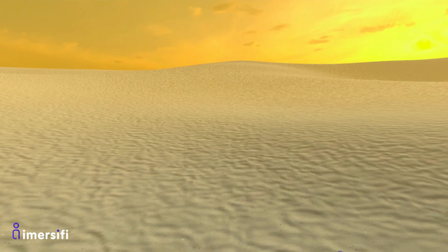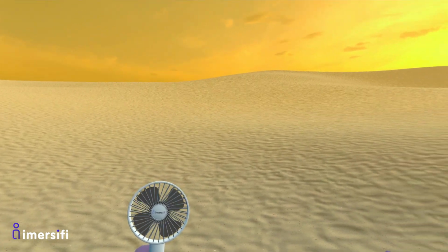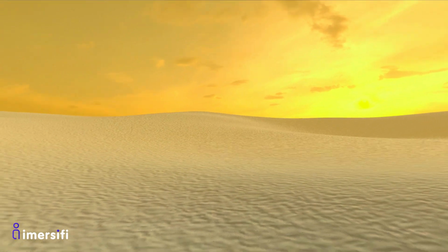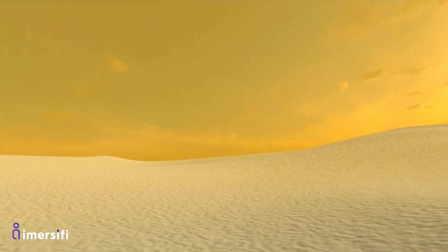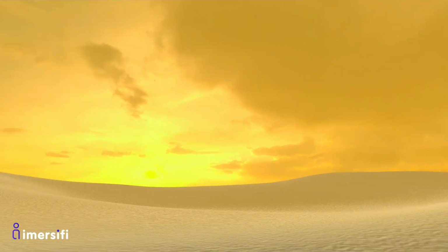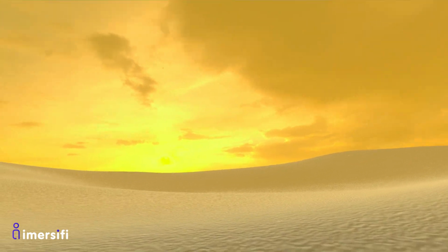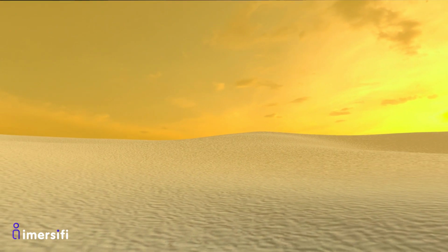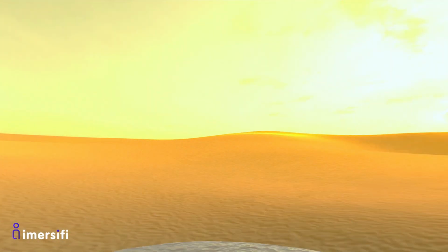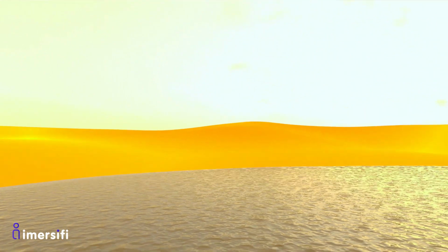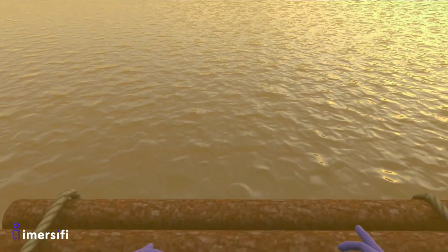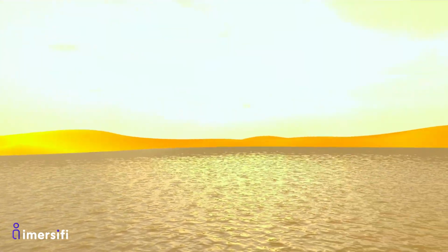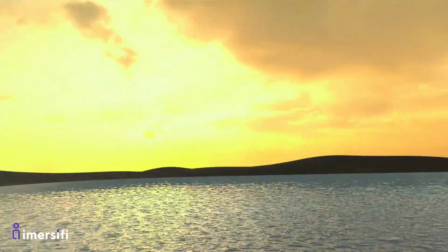Why do we find ourselves in the middle of a vast desert, under the scorching sun? Well, to make semiconductor devices or chips, the process often starts with sand or silicon dioxide. This sand is silicon-rich. When exposed to temperatures greater than 1800 degrees Celsius, the sand melts. The oxygen can be removed, and the silicon is purified. Now we have a lake of molten silicon.